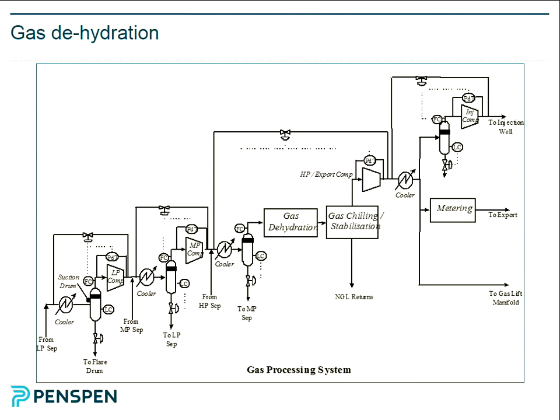Then you get dry natural gas, and the glycol is separated, boiled, and then recirculated. So you've got two fluids, you've got fluid circulation. You've got rich glycol, rich in water, coming out the bottom. You remove the water and then put it back in again. So it circulates. It's the way of removing water from your gas.